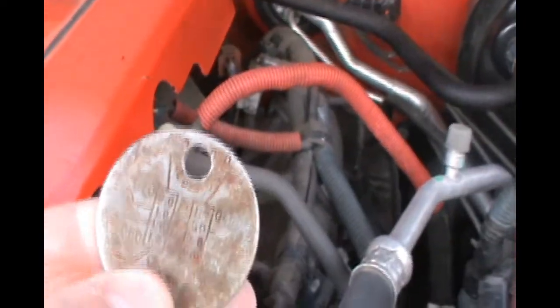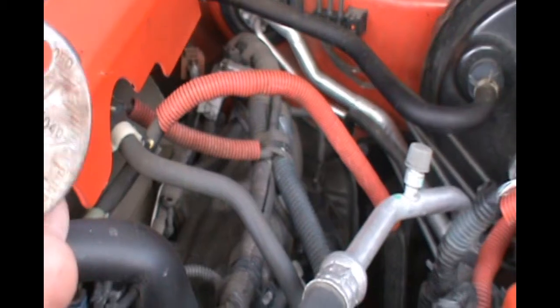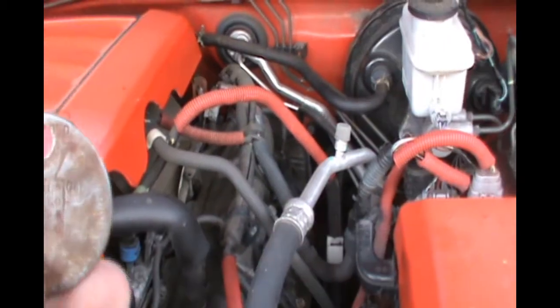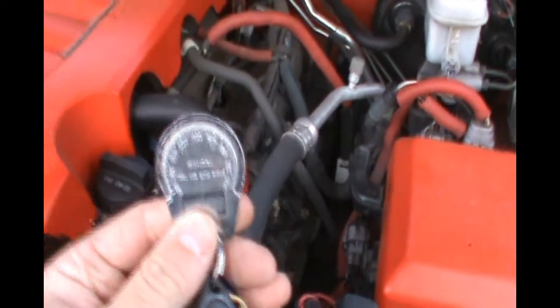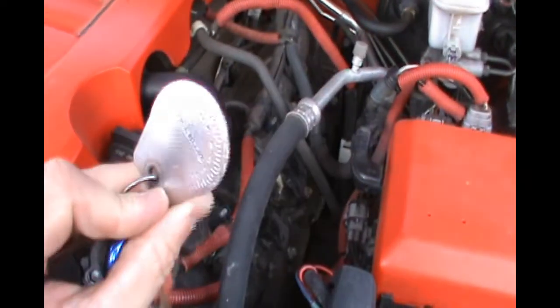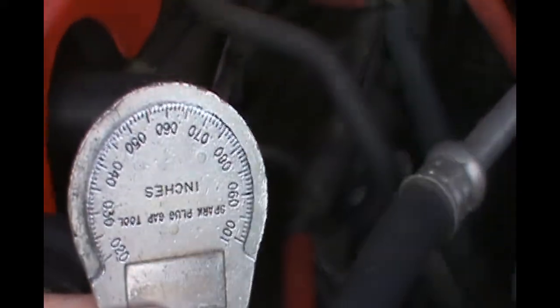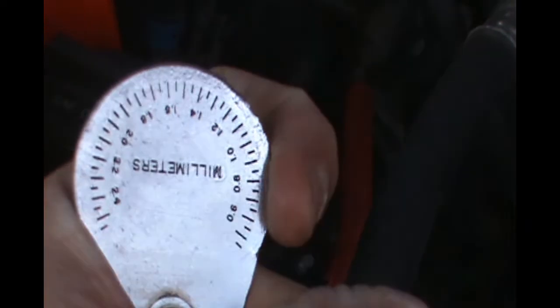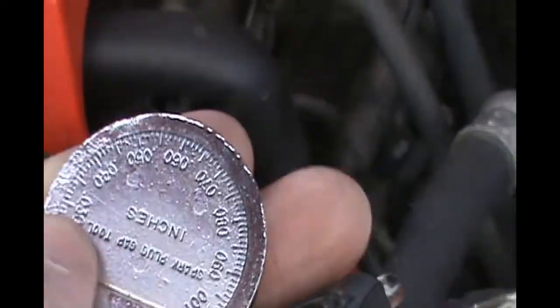So, on the back you can read it has numbers, both in metric and in standard. And it has all different sizes. Now, this is not the perfect example because it is dirty and it's old and used. So, I have another one. This is a Champion spark plug gapper that I got from Champion Spark Plugs from completing some training. And very, very simple. I always keep it on my keychain, lots of keys. And on one side it has the standard measurements in inches, and on the other side the metric measurements in millimeters. So I know what my spark plug gap is supposed to be. I find it on this dial. Right there, there's 30 to 35, and I measure my spark plug.